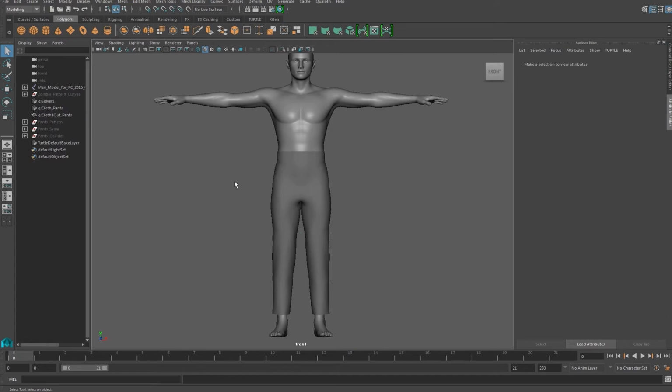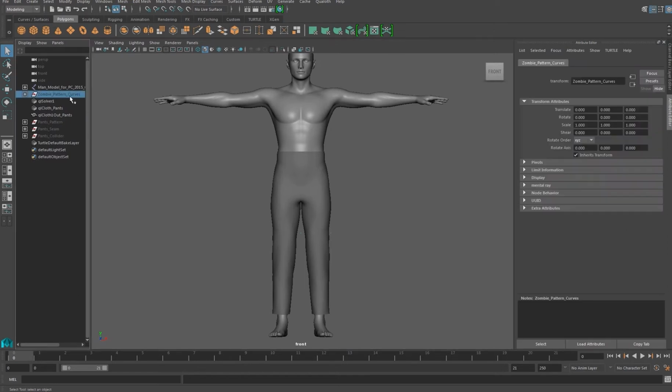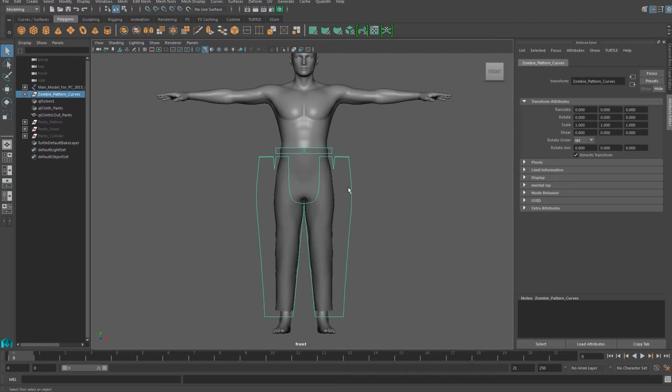Now, turn custom mesh's pattern curve group to unhide. If you have the constraint that was made beforehand, make sure you delete them all. We delete the constraint because constraint vertices' inherent index numbers are changed while editing the curve. The constraint that's made with previous inherent index will crash to constraint vertices. Make sure you check whether there is a problem in the constraint parts or not when your simulation stops.